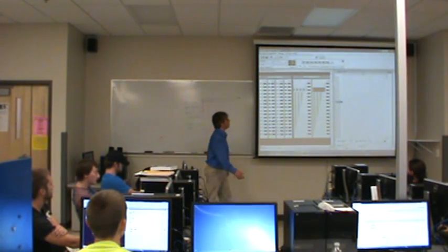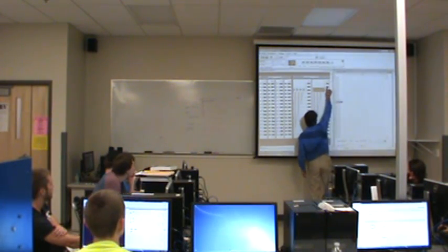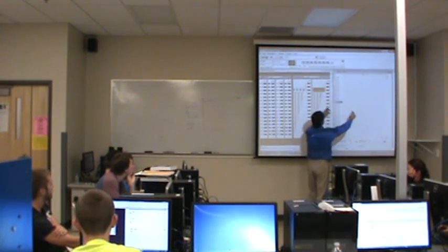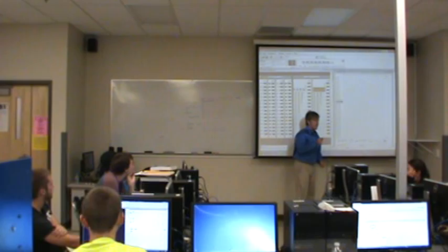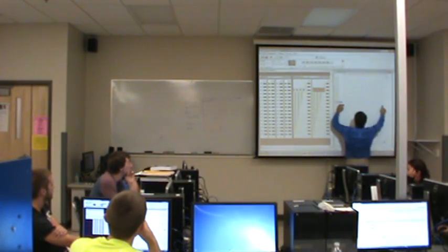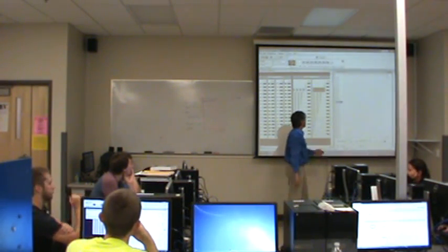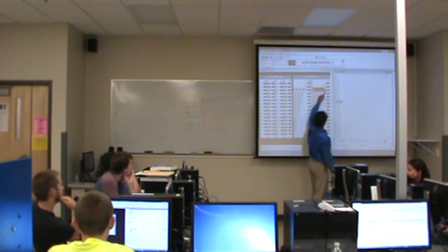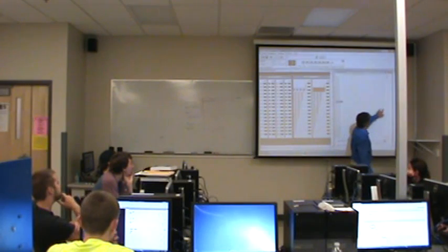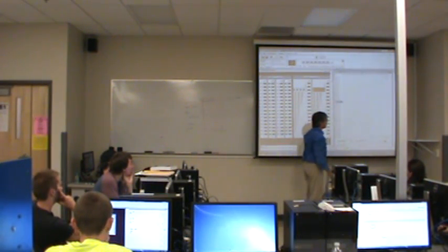So in the first step, what is it going to do? Well, it's basically going to turn on the 0th bit right there, and it's going to turn off all of these bits because there are all zeros here. So it simply copies that, pastes it there. And then when I trigger that instruction to go to the next step, then it will copy this line. So it'll turn off this one and turn on this one, essentially. That's what it looks like. But really what it's doing is it's turning off all of them and turning on this one. Next thing it'll do is it'll turn on both the lower bits. It'll turn on bit 0 and bit 1, and so on.